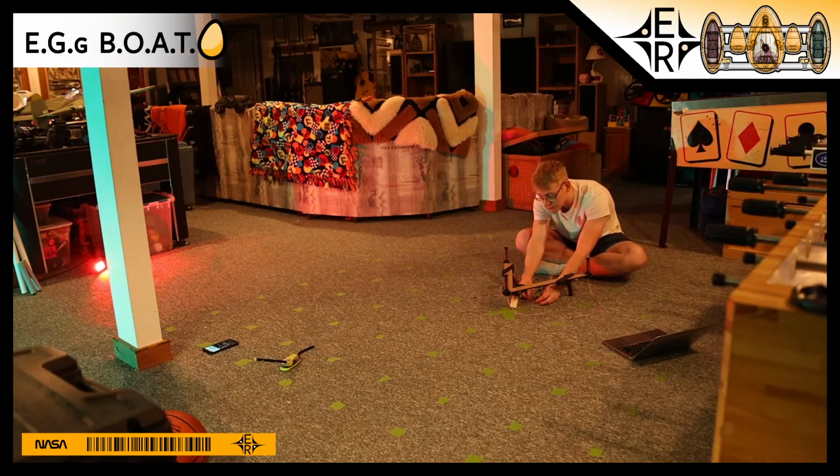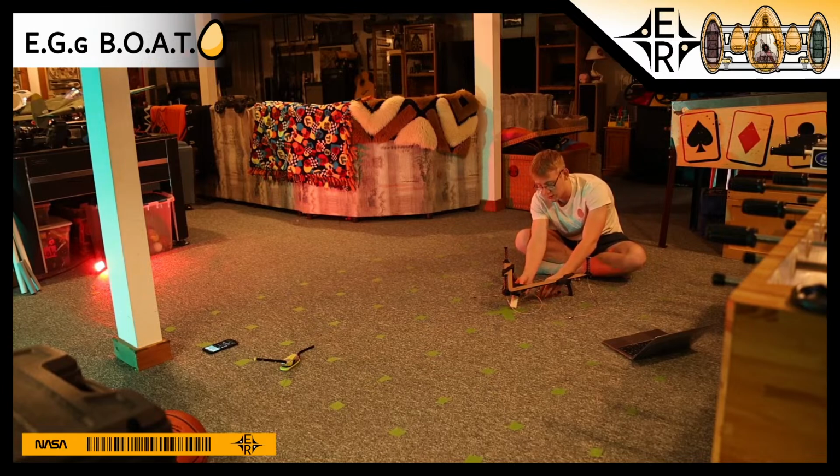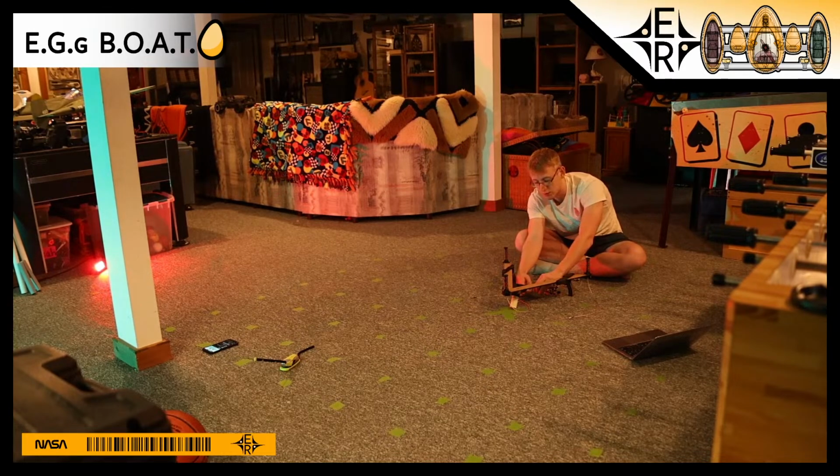So for your system, the front antenna is still going to be on the center of that X as the reference antenna? Yep. That'll go into antenna 1 in the phase comparison circuit. And there's two phase comparison circuits on the board. One will compare antenna 2 to our reference, and the other will compare antenna 3 to our reference. And our reference is just antenna 1. So we'll just take the angle for antenna 1 to always be 0, and then antenna 2 and antenna 3 will have angles relative to it.